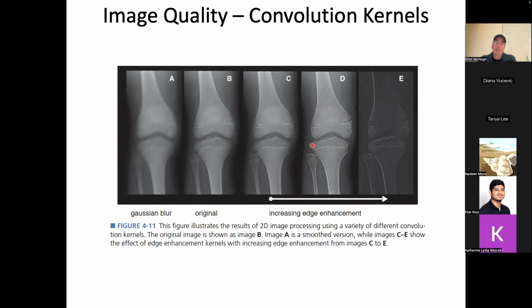So this looks a lot sharper than the original one because I have increased the power of these high spatial frequency components, or these edges, and I get something that looks sharper. Again, on your phone, you've got a slider and you can say, make my picture sharper, and it will take one of these filters and make it sharper, or you can blur it. Depends on your goals for your picture.